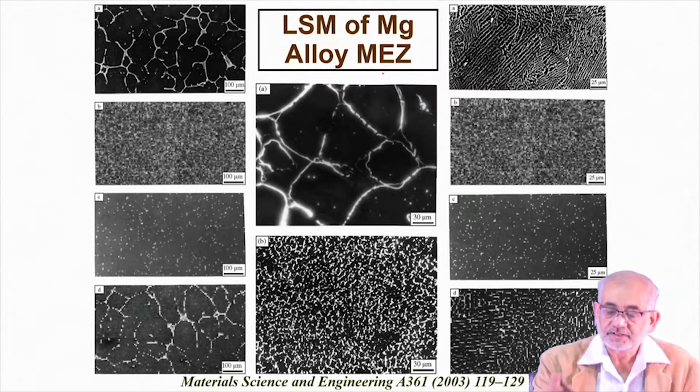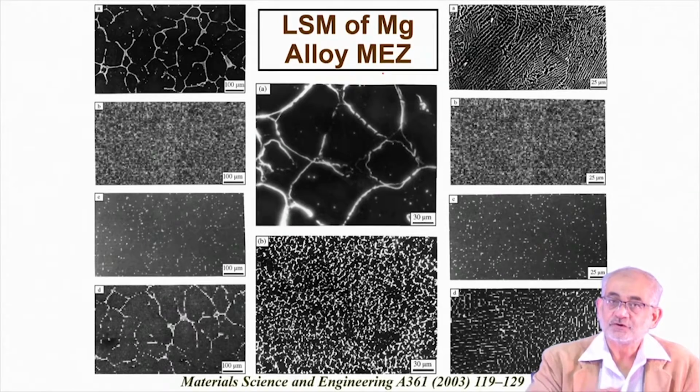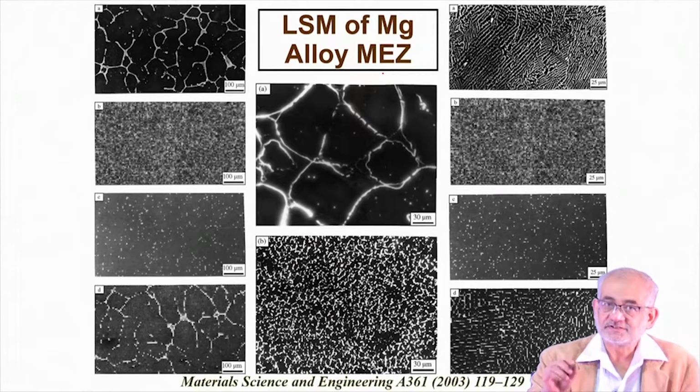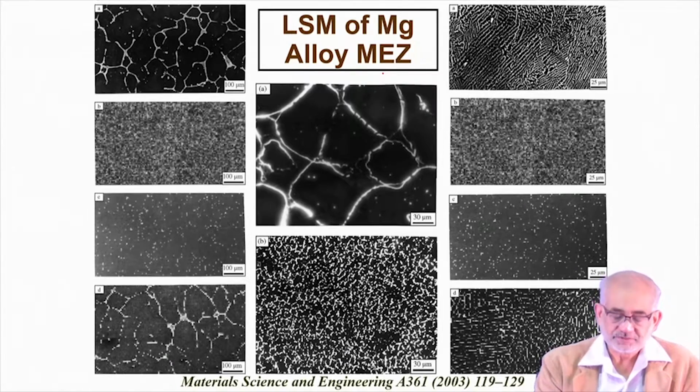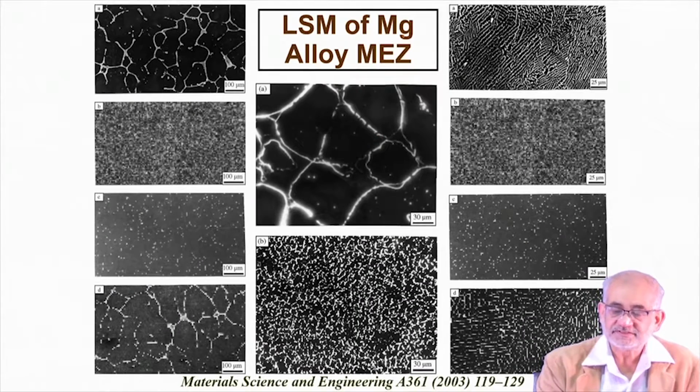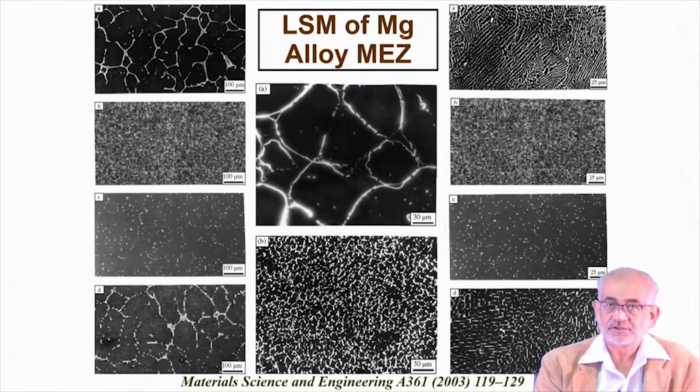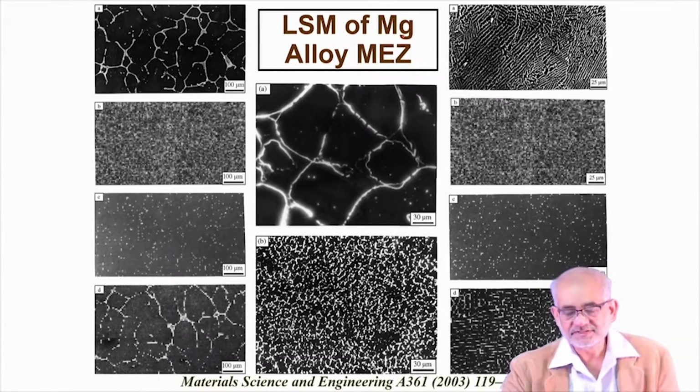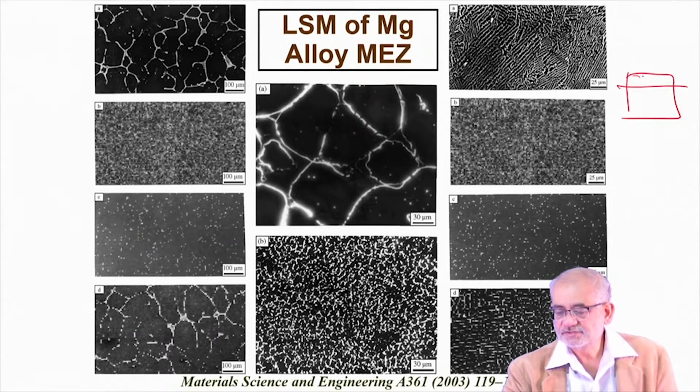In the previous two cases, I emphasized that we should remain below the solidus temperature. That means we don't want to create formation of liquid, either in small volume or large volume, because liquefaction followed by solidification will create residual tensile stress, which is what we don't want. But if we are dealing with magnesium or aluminum alloys, low melting non-ferrous alloys, we can easily melt the surface. So if this is a bulk component with such a coarse microstructure, then we can convert this by surface melting.